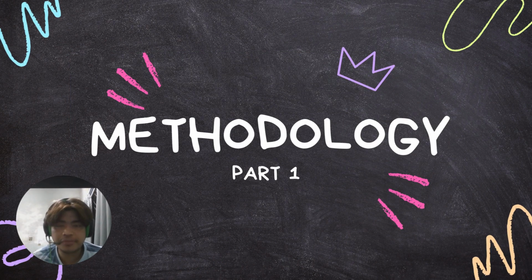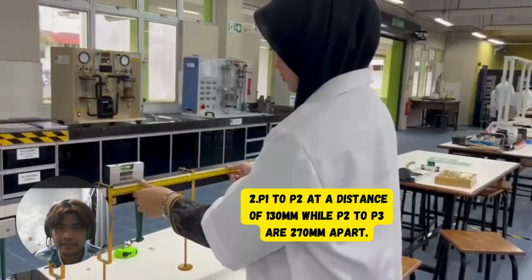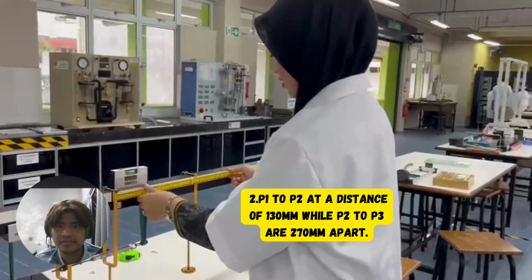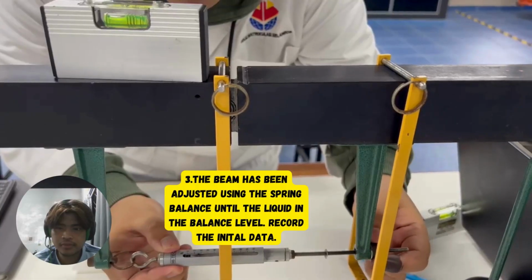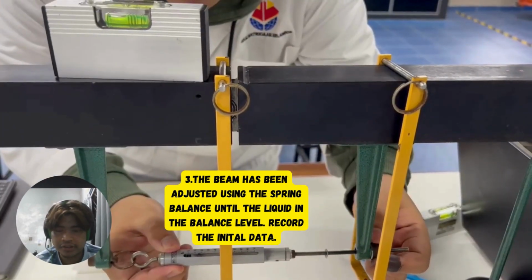Now I will present about methodology part 1. So first, the beam has been set up. Second, P1 to P2 is at a distance of 130 millimeters, while P2 to P3 are 270 millimeters apart. Next, the beam has been adjusted using the spring balance until the liquid is in the balance level. Record the initial data.